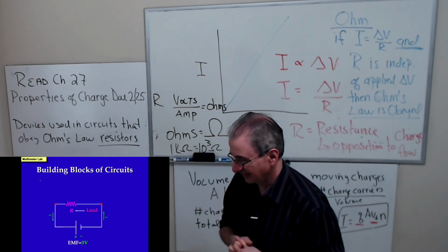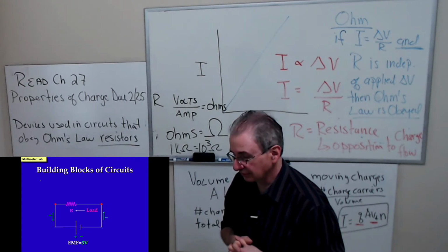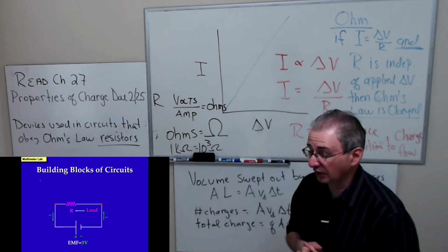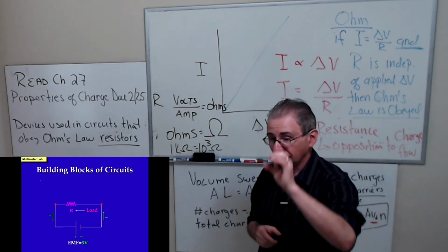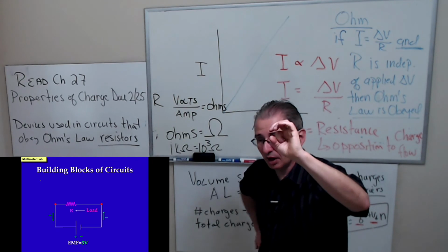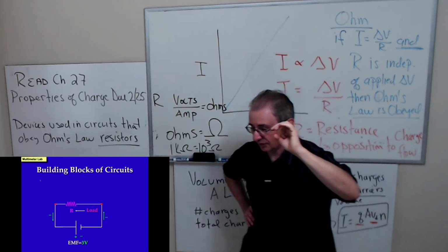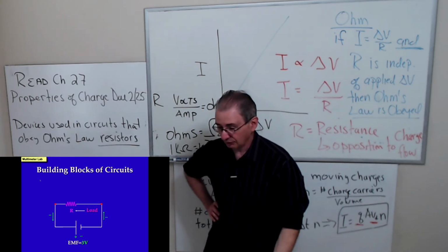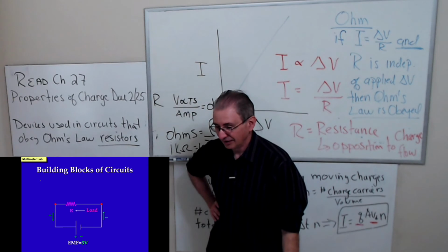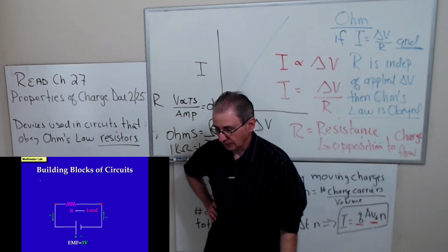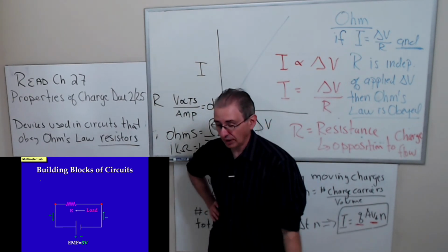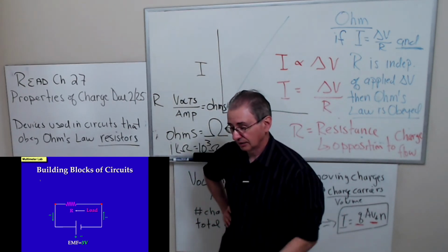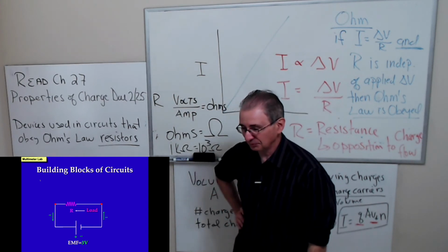Yes. So can we melt a wire with current? Oh, absolutely. Wires are rated for current. The smallest diameter wire can't take much current as opposed to a thick wire. When you go to a hardware store and buy those big utility wires, they're rated at various currents, because the higher the current, the more energy is going to be dumped into the wire.